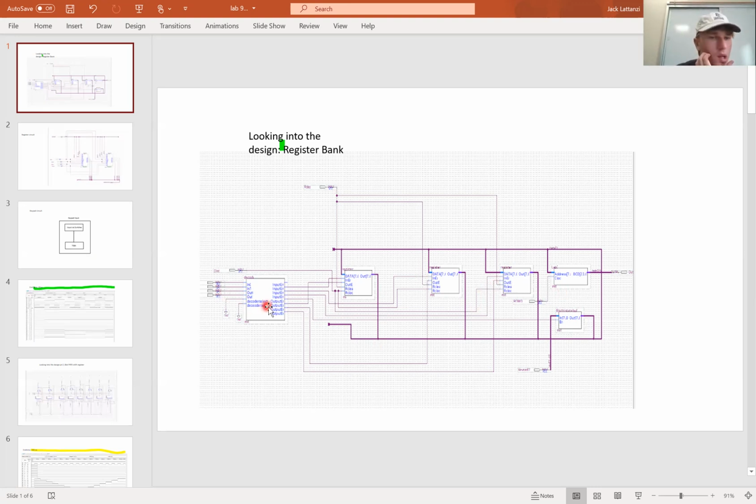Okay, so another way that this circuit works is that there is a clock pulse, which is common for all of them, as well as a clear up here, common to all of them. So we can clear the registers, and the clock pulse creates movement.